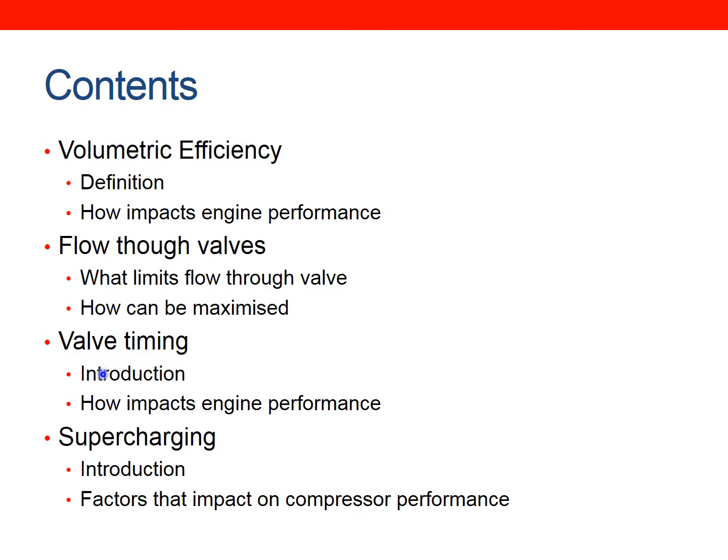Valve timing: we talked about why the correct amount of overlap between the exhaust and intake valve is a good thing, and how advancing or retarding the valve timings, whether they're opening or shutting, impacts the engine. And then finally we talked about supercharging, so the fact that we can increase the density of the air to get a higher mass of air into the engine for the same volume, and what factors affect the compressor performance, such as stalling and choking.